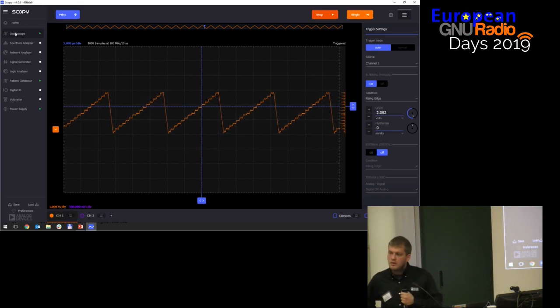The FPGA also has interpolation and decimation. It's a little different because the chip is different, but it's basically the same principle. It's not the same chip? It's not the same chip. We use the AD9963 chip, which is kind of an instrumentation chip. But for the Pluto, we use the AD9363, which is an SDR. But I guess the FPGA is the same FPGA. It's the same FPGA. Okay.